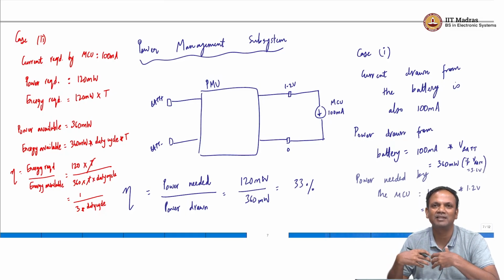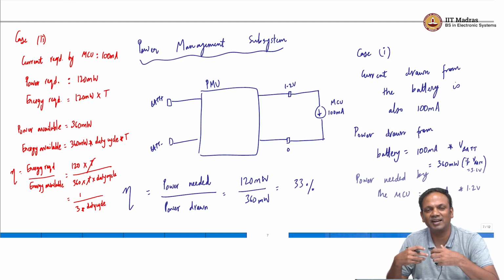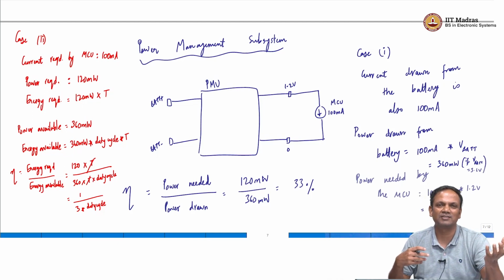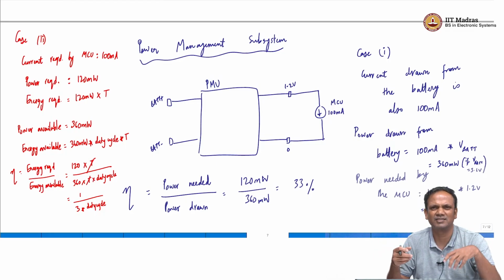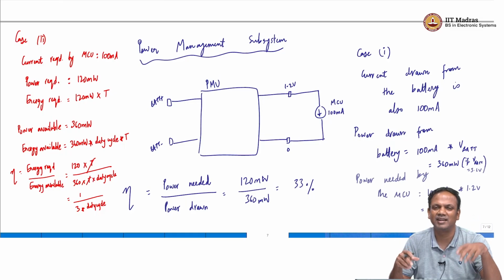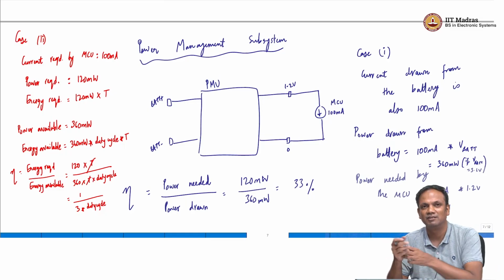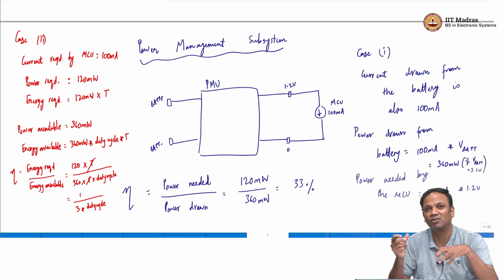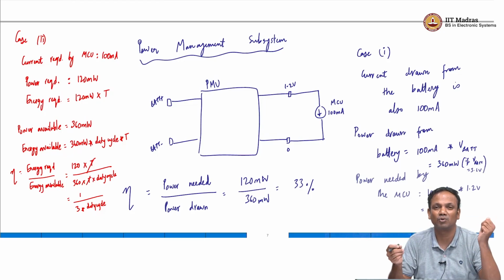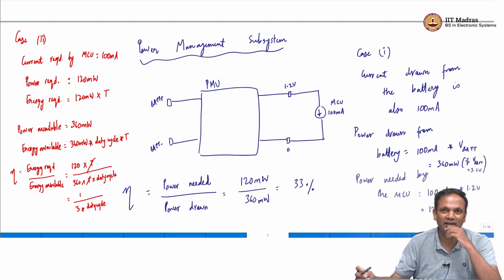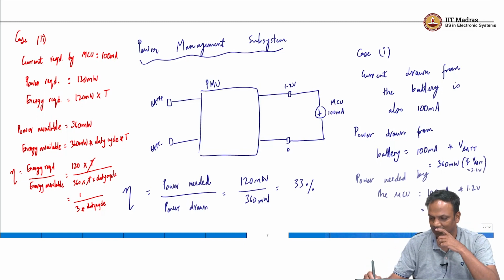Different applications might demand different answers, but once you have the underlying knowledge of what is the pro, what is the con, then you can weigh the trade-off and say, for this application maybe this is the right use case. So, where you are driving an RF, you might say, actually for RF I am particular about keeping that supply clean, and anyway it needs a high supply, so efficiency is really not a problem, so I am going to drive it with an LDO. Whereas for the microprocessor, you might say that tends to take a lot of current and the voltage difference is so large that it is better to drive it with a switching regulator. So, these are choices that you will make as the system engineer.